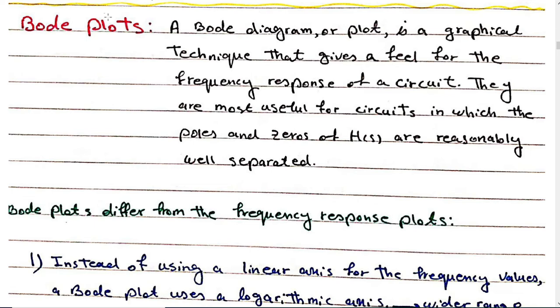It is very easy. If you show me the plot, I can tell what kind of circuit you have, whether it is a low pass filter, high pass filter, or whatever, and I can understand the cutoff frequency or frequencies and the gain of the circuit. That's why we use Bode plots.